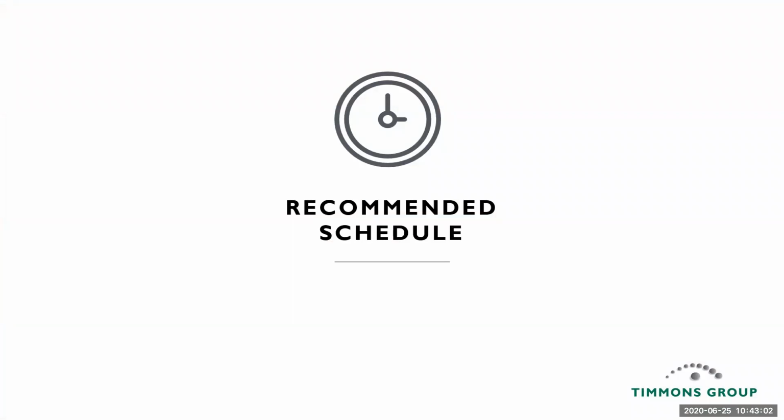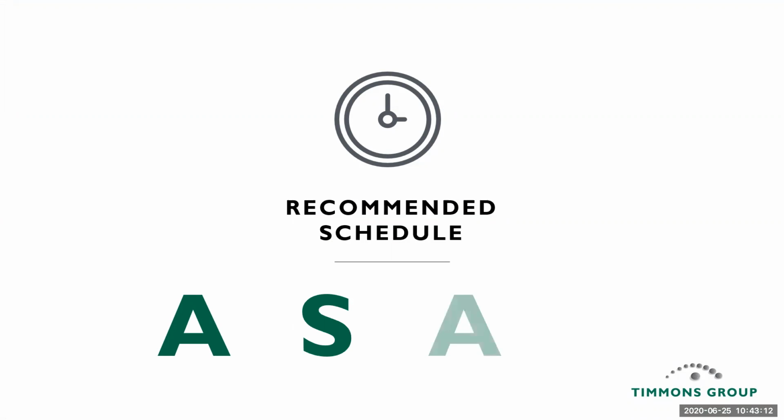I would offer that the last thing an owner may want is to purchase a property, secure funding, maybe go through site plan approval and all of these steps just to find out that the downstream sewer is incapable of handling the anticipated project flows, and several hundred thousands of dollars or millions of dollars will be necessary to improve downstream capacity.